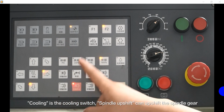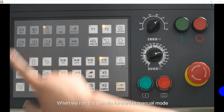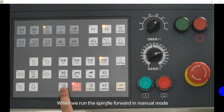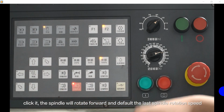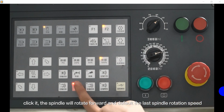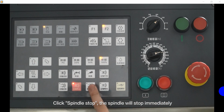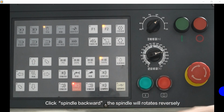Spindle upshift can upshift the spindle gear. When we run the spindle forward in manual mode, click it, and the spindle will rotate forward and default to the last spindle rotation speed. Click Spindle Stop, and the spindle will stop immediately. Click Spindle Backward, and the spindle will rotate reversely.